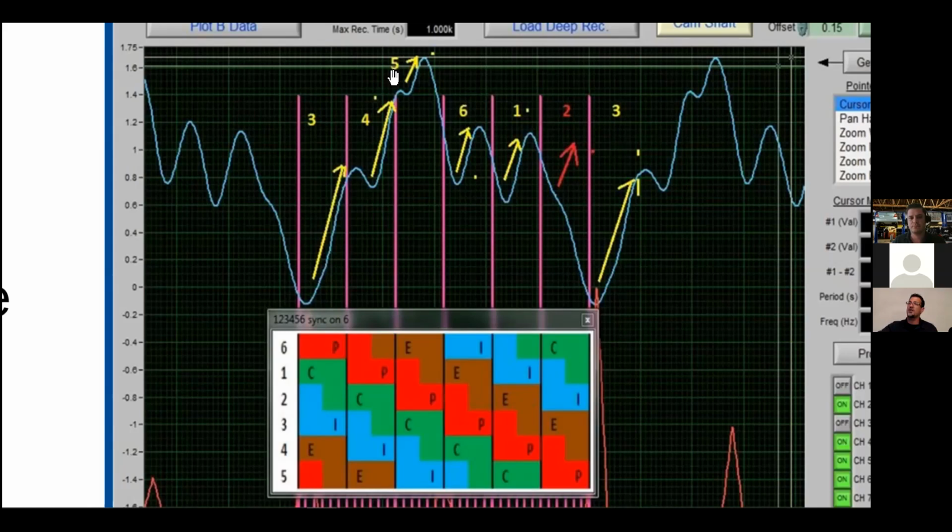And then you have to ask the question, how come vacuum depleted right here? Well, the next cylinder in the firing order, not cylinder number 2, but the following cylinder, cylinder number 3, is starting its compression stroke here and finishing it here. Cylinder number 3 has nothing wrong with it. It has integrity, meaning it's going to load the starter, it's going to load the crankshaft, load the piston, and it's going to slow the crankshaft down. And if we slow the crankshaft down, vacuum is going to subside a little bit. Please raise your hand if you're with me.